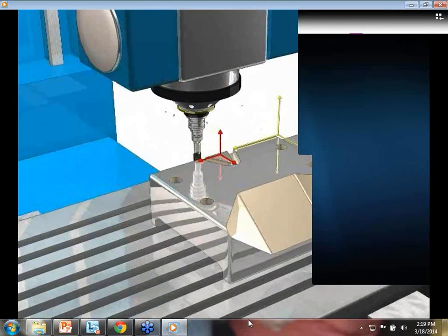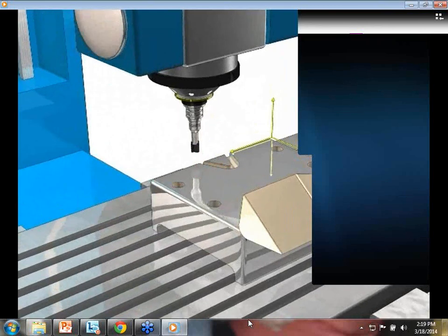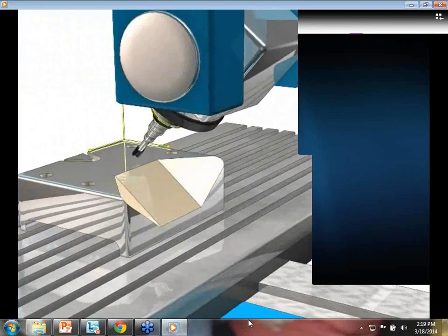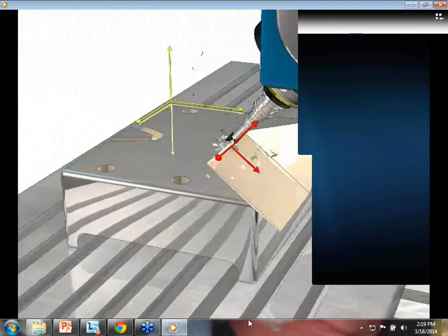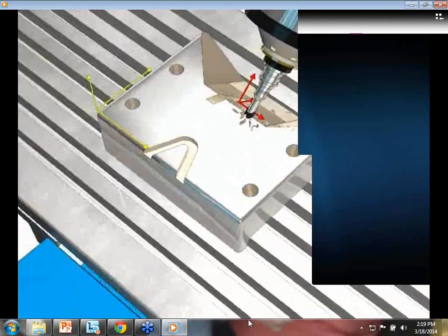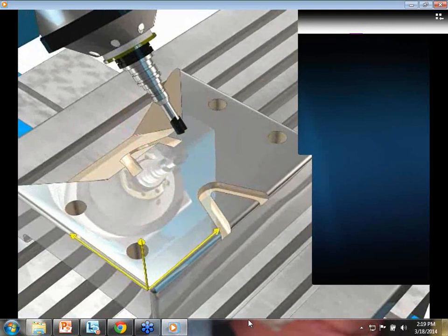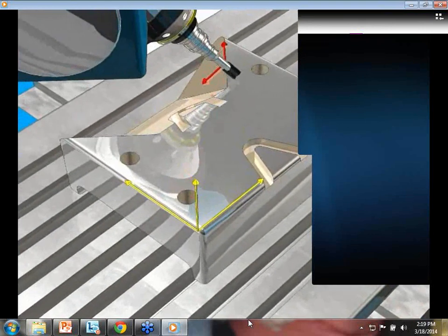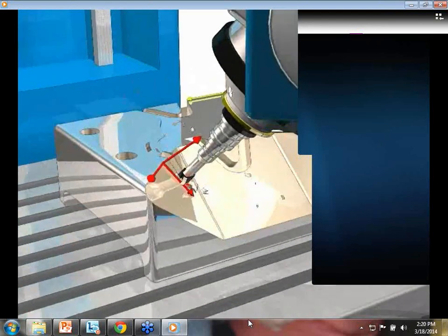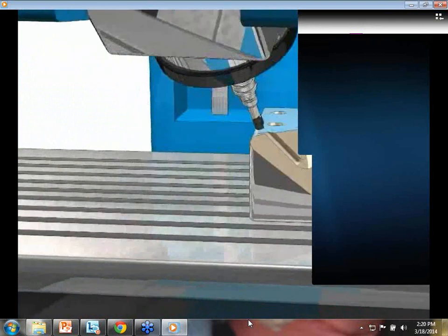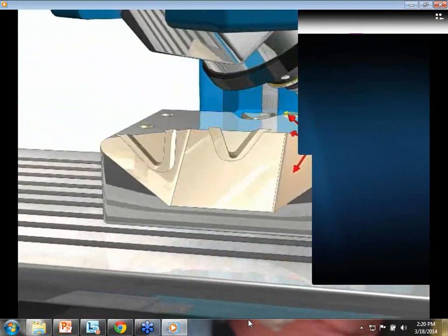So it's machining this V in your standard XYZ. Then it does it on a tilted surface, and you can see how it shows the different work coordinates, with the 3-finger rule there, like Eric always used to say. And then you can tilt it another direction, still use basically the same program. It's cutting the same shape, but on a different angle. And then you just tilt it around and go do the other side.